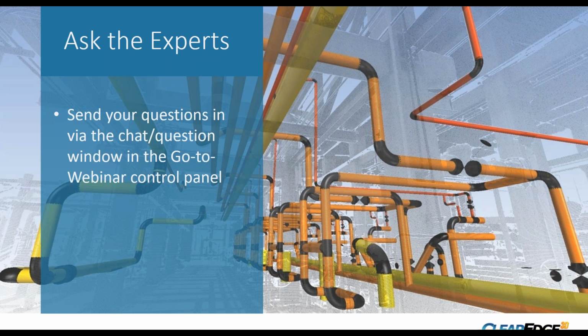So how does Verity compensate for high gloss steel piping and ducting? So the way our algorithms work, without getting too deep or giving away too much of the ingredients of the special sauce, we're basically fitting geometry to points that we find around the object and looking for what the best match is. So you may have noticed on the analysis tab there's a checkbox for indoor scanning. We have that checkbox because if you're outside and there's holes in your data, it's probably because the sky is there. If you're inside and there's holes in the data, it's probably because there's a highly reflective material or a very dark, rough material, something that does not reflect laser light very well.